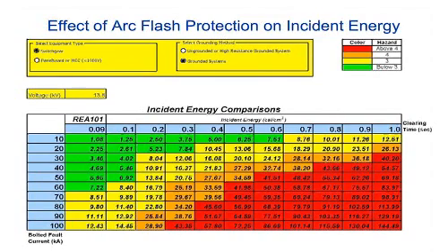You can see that as time goes down, these are the incident energy going out that way, this is the voltage fault current, and these are the clearing times in seconds. So if I'm at 53 milliseconds, I'm way down here in that curve. What that does is it forces all those cells towards that direction.